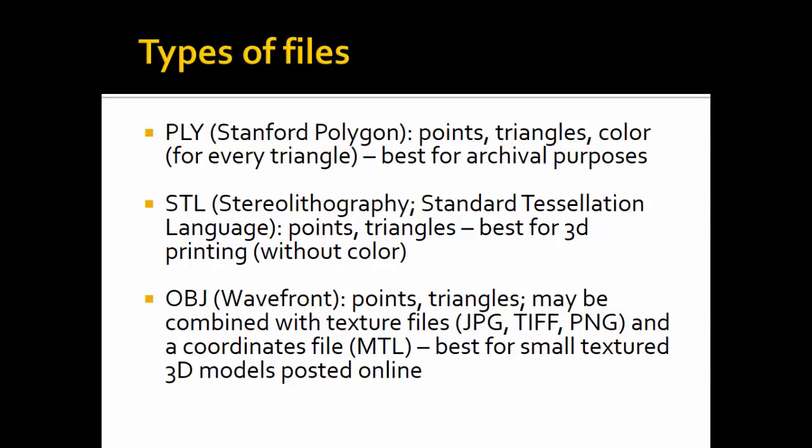The most common format used in printing, on the other hand, is STL, stereolithography, also called standard tessellation language, but that's a retrospective acronym. It's not the actual name. And this technology is used by most 3D printers, obviously those which do not print in color. And then a lot of online data, or the data meant to be shared online, is in the OBJ, or Wavefront, format.